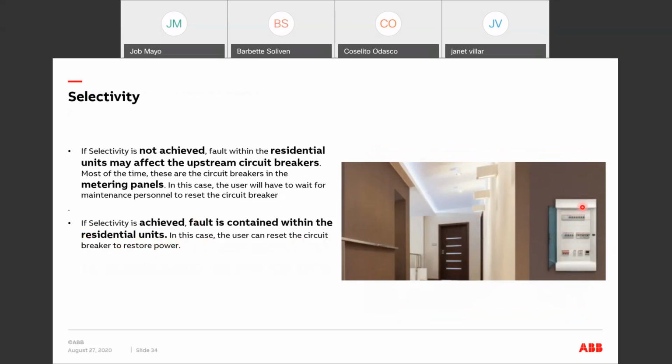However, if we use a 60947-2 circuit breaker within a residential facility, it's not that there may be some hazard, but a circuit breaker under the 60947-2 standard and not tested under 60898-1 is not tested for non-trained personnel. So you'd need a trained personnel to reset or operate the circuit breakers if we use a 60947-2 circuit breaker within the residential units.